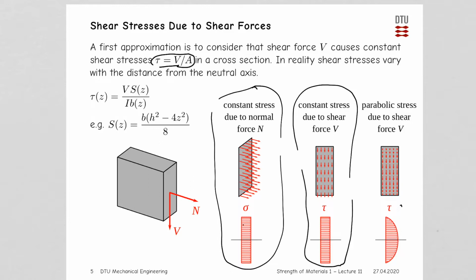At the top of our cross-section, here and here, if we look at advanced equilibrium conditions, we can actually see that we cannot have transverse stresses at those points, because it has to be in equilibrium with the stresses on the top of the beam, and there we do not have any stresses, so they must also vanish very near the cross-section top and bottom points.